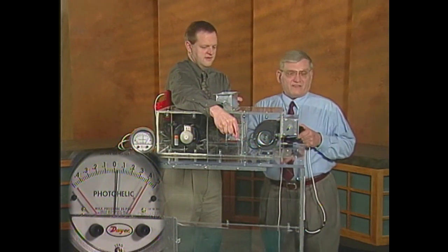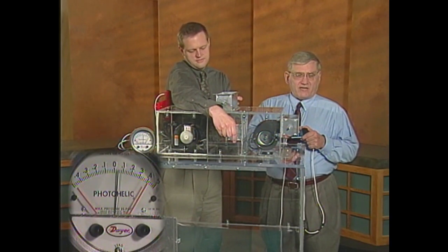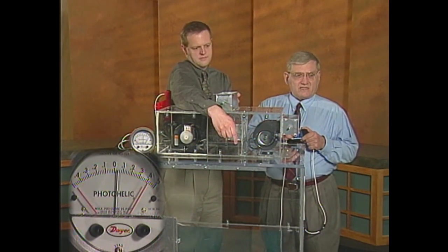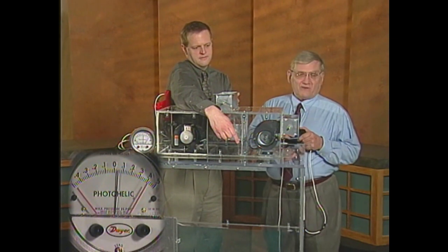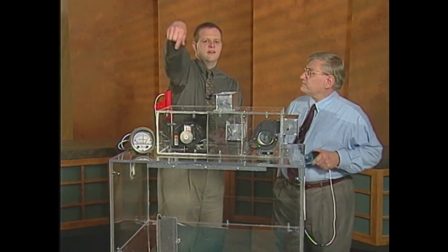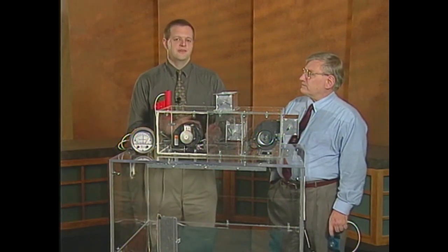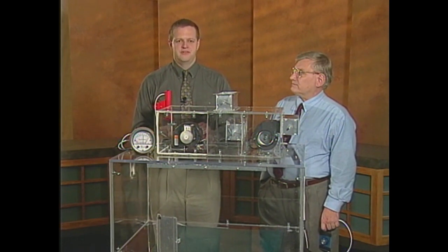100% outside air. Yep. Now John can modulate the outside air back slowly. As he does, I will reduce the exhaust rate, pretty much keeping it within the control band that we would like to have for the building. John, this direct method of controlling the relief fan allows the system to dynamically respond to changes in building pressure.